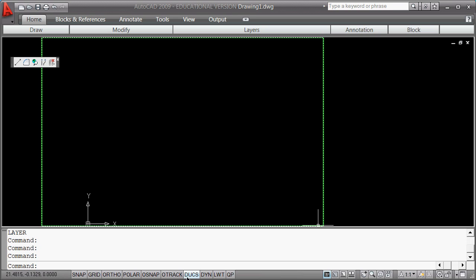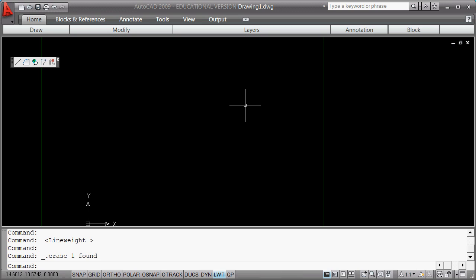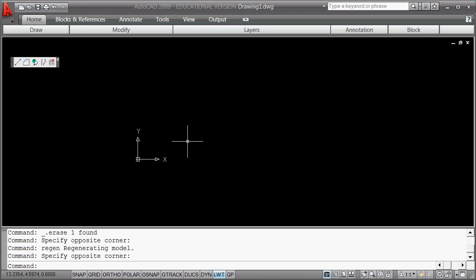In mathematics, points do not have any presence. They are just telling you the spot. So when I click on the line weight here, you see that it kind of thickened up. I clicked on it, I can hit delete, click on something again, hit a regen, R-E-G-E-N, which is a good one to clear your screen. I have no idea why those are kind of ghosting right there.